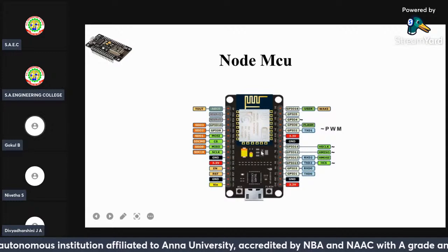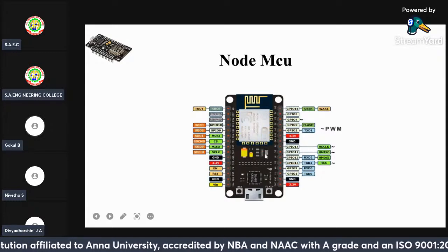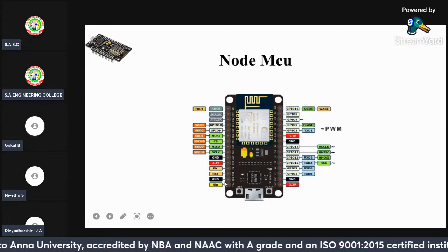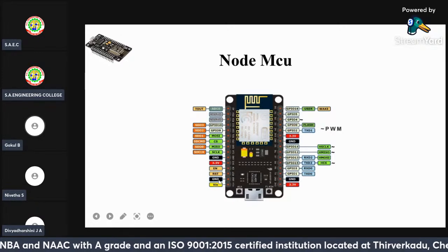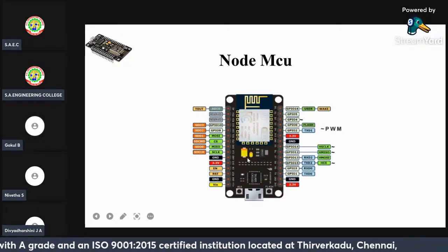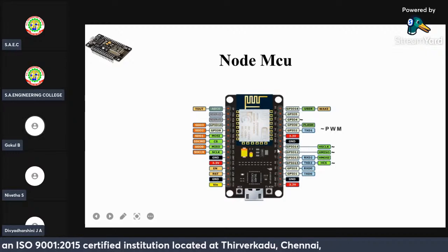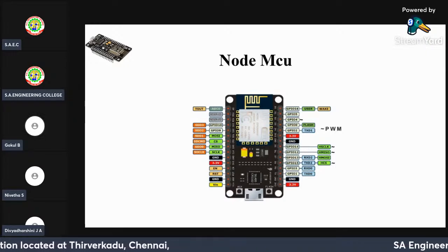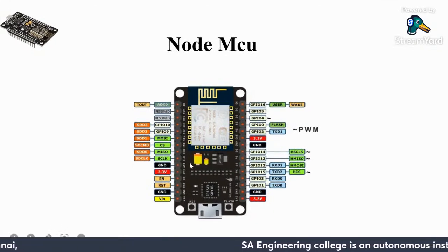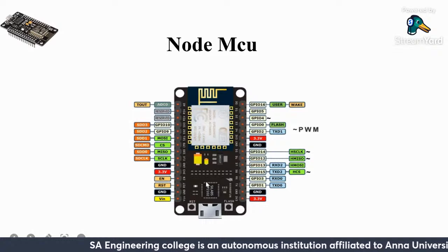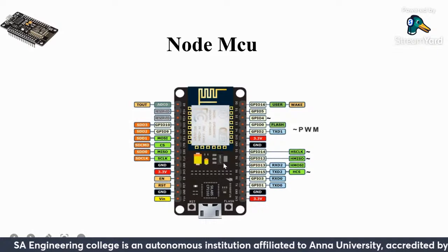And this one is the regulator which converts the 5 volt input. Using either the micro USB or the Vin and ground supply, we give that input. But it should be converted into 3.3 volts for certain sensors or other things. Using this regulator, we convert that 5 volt or 8 volt supply into the corresponding 3.3 volt supply.